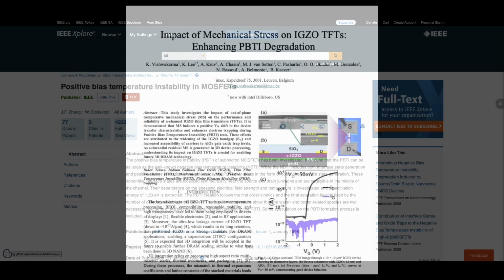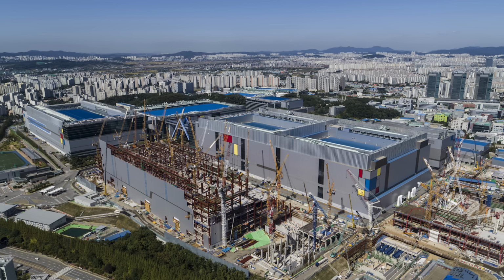Nevertheless, the 2020 IMEC paper triggered a flood of new research across the world, and IGZO has been added to various long-range roadmaps relating to the DRAM industry. That does not mean it is going to make it to fab floors. There exist other competing concepts, including an intriguing one that uses thyristors, but IGZO is a serious contender. Since these stackable options are not yet quite ready for prime time, the current situation is to stack more DRAM dies, HBM and advanced packaging.